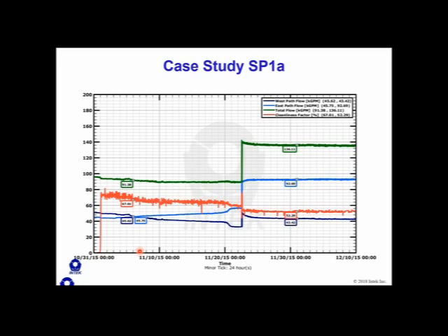And so when that starts blocking up the cooling water going into the west path, the flow rate through the west path decreases. Well, the pumps are still trying to deliver the total cooling water flow rate, but it can't push that flow rate through the west path, so the east path flow rate goes up. The reason for the total flow rate decrease is that because of this obstruction, there is now additional head pressure on the pumps. And so the total flow rate that can be delivered from the pumps is affected by that head pressure, and the total flow rate decreases due to this plugging.